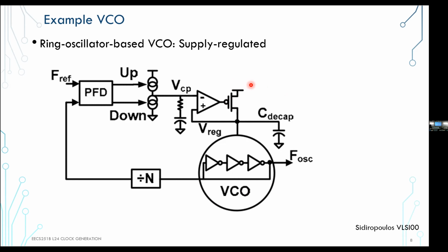The alternative is that you have to bring in very clean supplies, so-called analog supplies, and route them on the chip to where you're installing the PLL, making sure they're properly coupled, or even an analog VSS. There are different theories about that, but that's extra floor planning work you have to do to protect the PLL supplies. But if you add the regulator, you have a somewhat more relaxed environment.